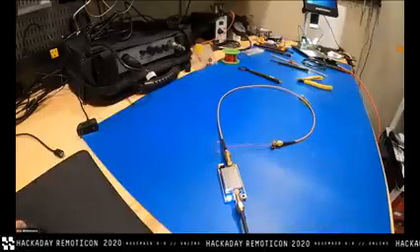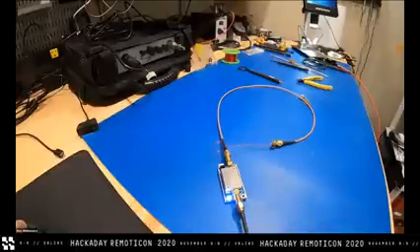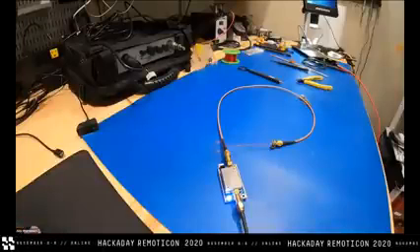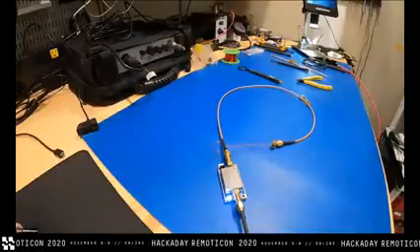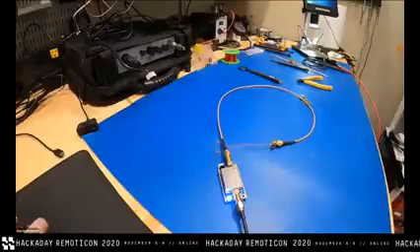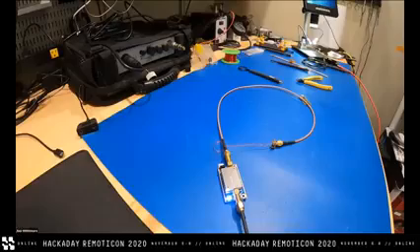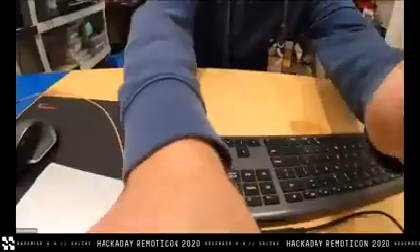So first things first, if you've got your virtual machine open and running, you want to pass through your SDR device to that. I'm running Parallels, so this happens automatically because its performance is just a little bit better than VirtualBox. VirtualBox kind of crawls to a halt, and I'll show you how and why. So go up to Menu, Devices, pass through your RTL SDR device, and that should be reflected. Yeah, so my RTL SDR is passed through.